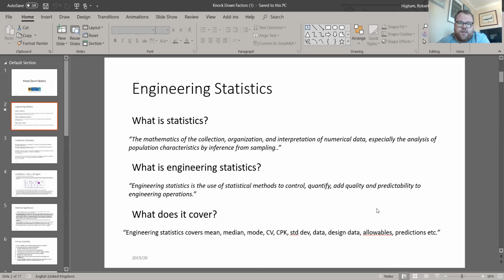So for example, the ultimate tensile strength of a material, is it affected by temperature? Is there a knockdown factor that can be applied? We'll sometimes call these knockdown factors a safety factor, but in reality, all of these terminologies are focusing on how we change the real data to make something predictable, or how we make something give us a higher level of confidence.